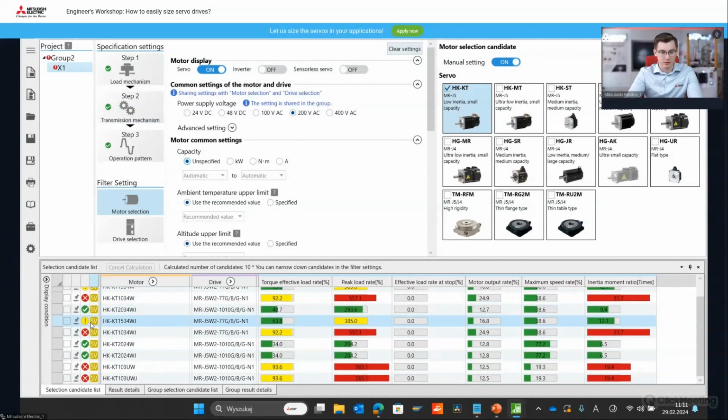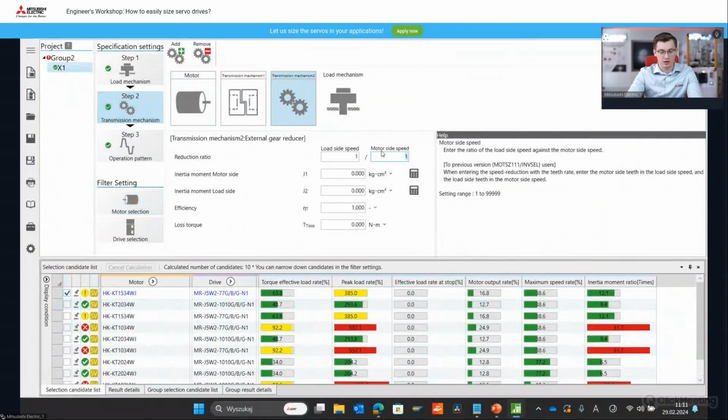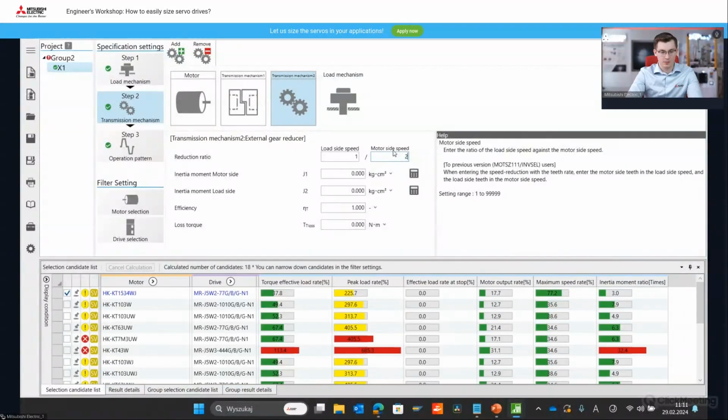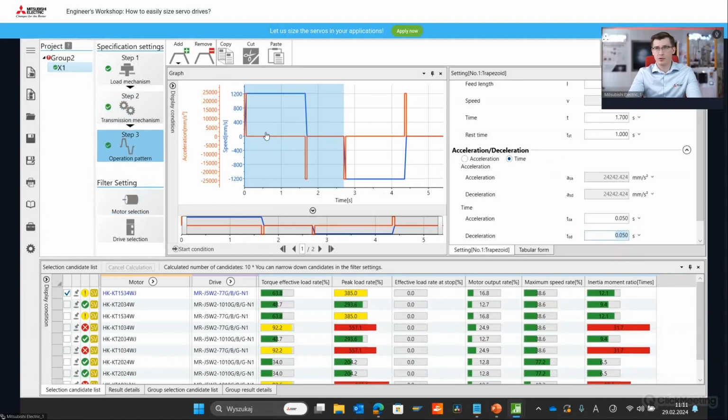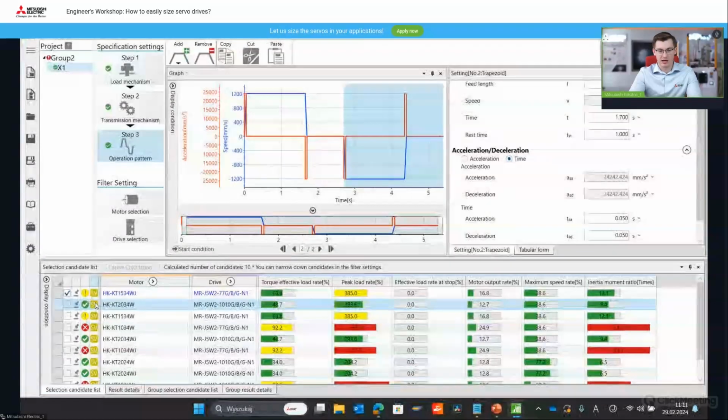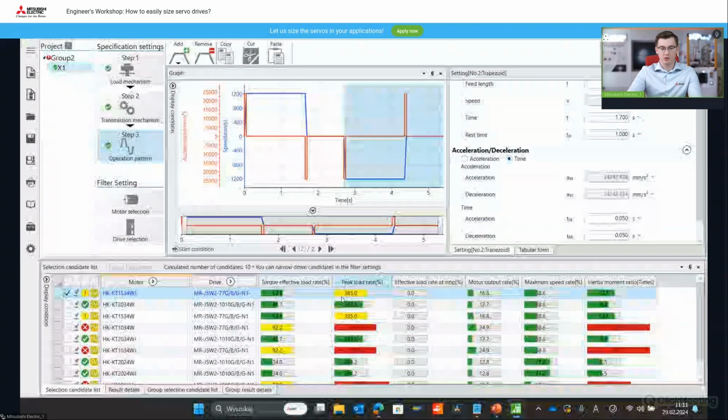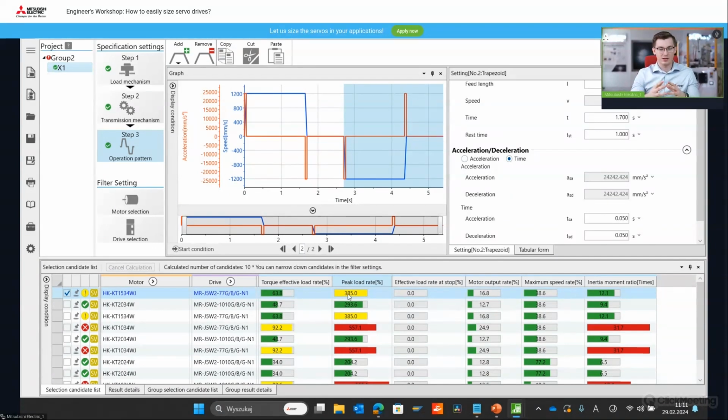So for example, I will check this motor and then check the gearbox. No, so it's better with one-to-one. Okay, so as you can see, I selected pretty much a very, let's say, very dynamic application. So we are going with motors that the performance of them are very strong. Yes? So the peak load is 4 times. 4 times, it means that the motors have 4 times bigger on the overloading, 4 times bigger torque than nominal one.